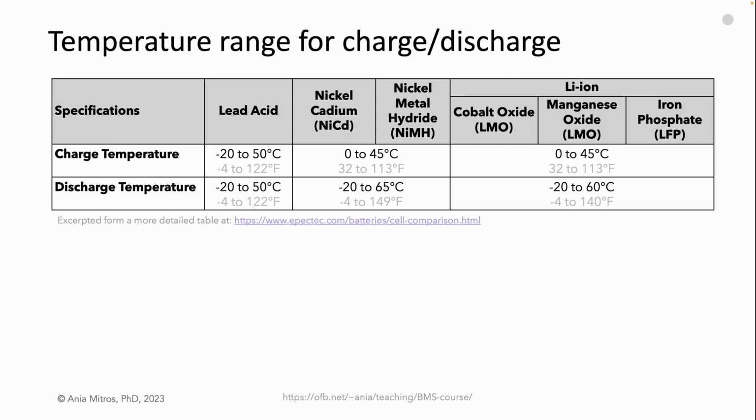Batteries operate best within about 20 degrees C of room temperature. This is true for all cell chemistries, though you can see that lead-acid batteries outperform lithium-ion below freezing. Fortunately, lithium-ion batteries operate well at temperatures that are comfortable for people, which makes them sufficient for many applications. For operation in extreme climates, either below freezing or above about 45 C, either a heating system or a cooling system or both are necessary.